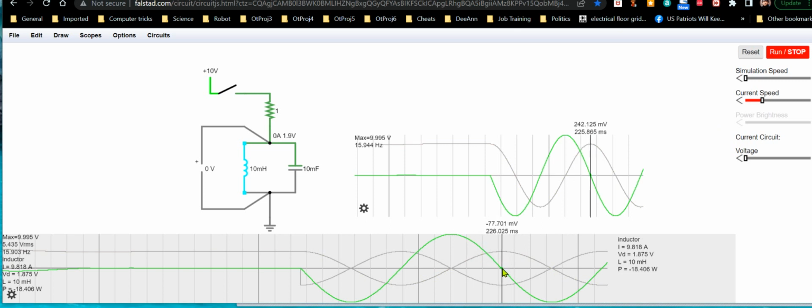discharging. So that's what you can kind of look at it as, the voltage waveform actually indicates the charge level of a capacitor, even though the inductor is actually generating the voltage you're seeing when the inductor is discharging. So when it's charging up the capacitor, the voltage is actually coming from the inductor. When the capacitor, like you see here, is charging the inductor, it's generating the voltage.